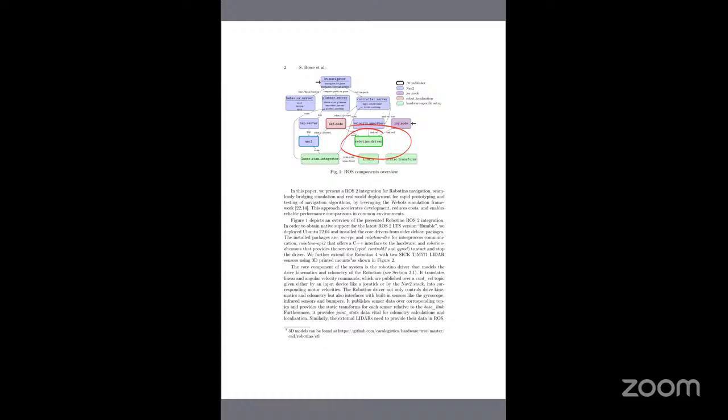Odometry. Odometry means how much distance this robot covered in X position, Y position, heading. Then the cmd_vel topic. In ROS2, to move the robot, we use a command called cmd_vel. For example, linear velocity 0.5 meter per second, angular velocity 0.2 radian per second.